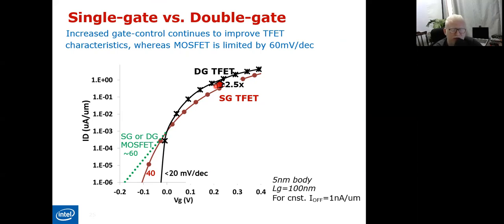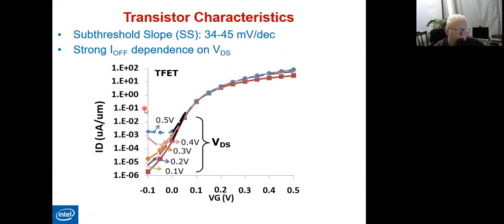multi-gate field effect transistors are also one of the very interesting structures that most of the fabricators, I mean Intel and IBM and all these, start to use whenever they narrow down the transistors or the MOSFET scale. Double gate, multi-gate transistors and thin gates, all these are very interesting in semiconductor devices technology. Here is another view for the transistor characteristics.